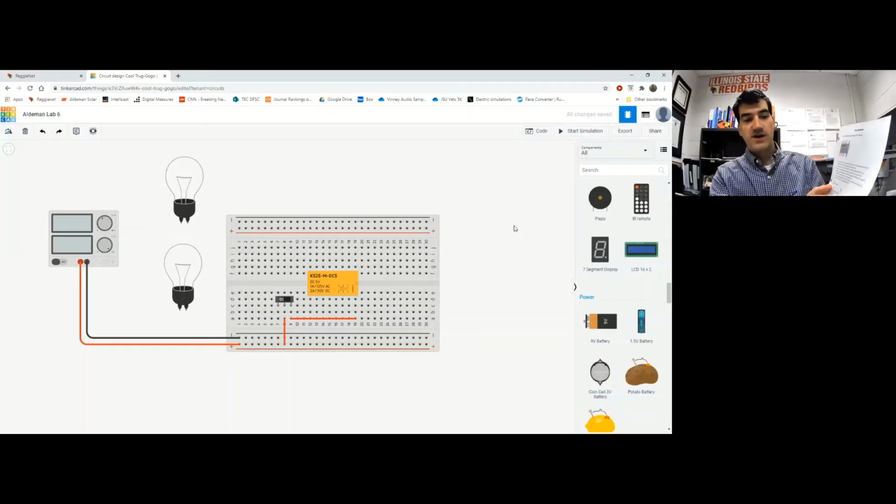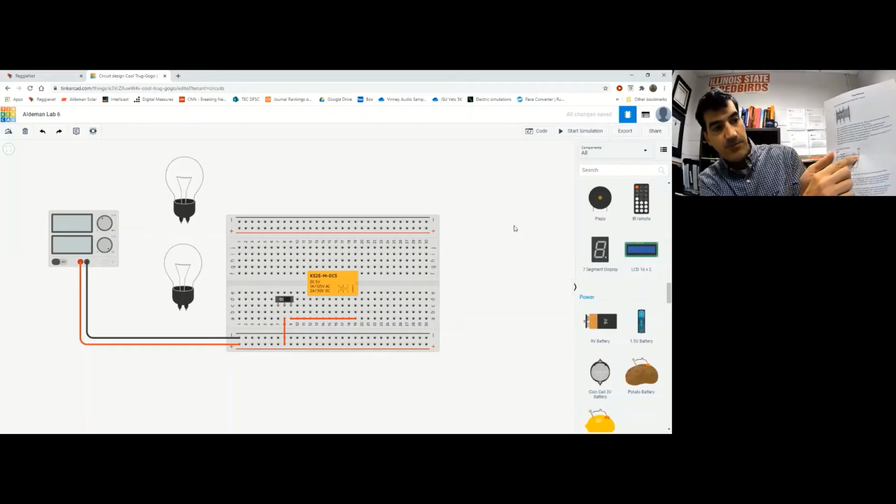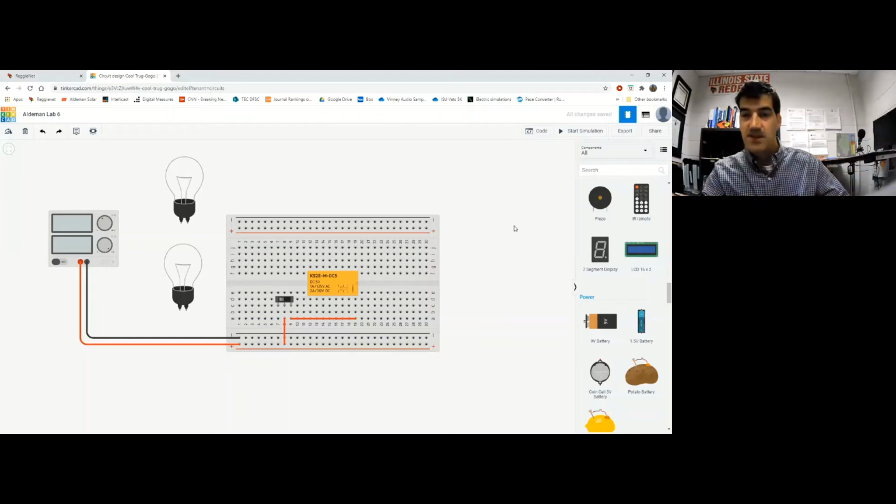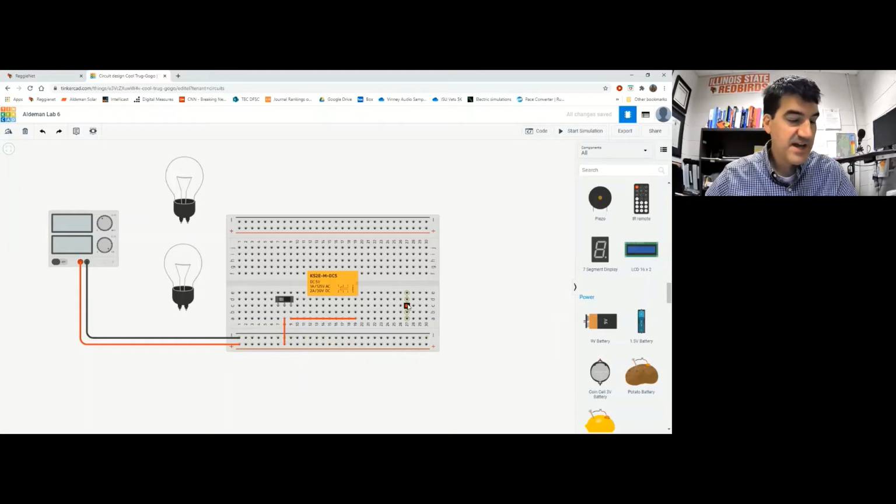And the last wire here goes from the output of the coil to ground. And ground is the negative rail right here. So the negative side of my coil is this connection. So anywhere up here will work. So I'm going to go from here to the negative side, and then I'm going to straighten it out a little bit. Okay. All right, and that should be it.